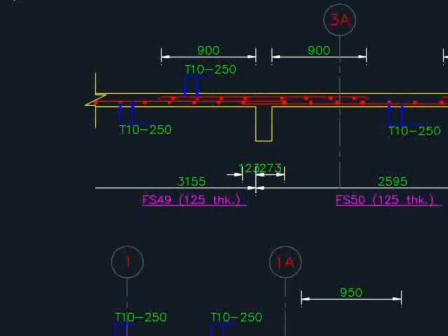If you choose to do so, you need to make sure when you do the calculations, especially for this slab, the effective depth d is calculated accordingly, and you need to make sure with the reduction in effective depth, because you purposely swap the arrangement of the reinforcement bar between the main and the secondary, the slab must pass.